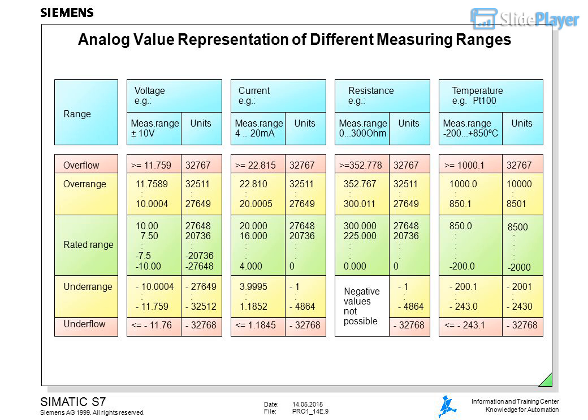Voltage, current: encoding the asymmetrical voltage or current ranges. Asymmetrical: 0 to 2 V, 0 to 20 milliamperes, 1 to 5 V, 4 to 20 milliamperes. Results in a rated range of 0 to plus 27,648.